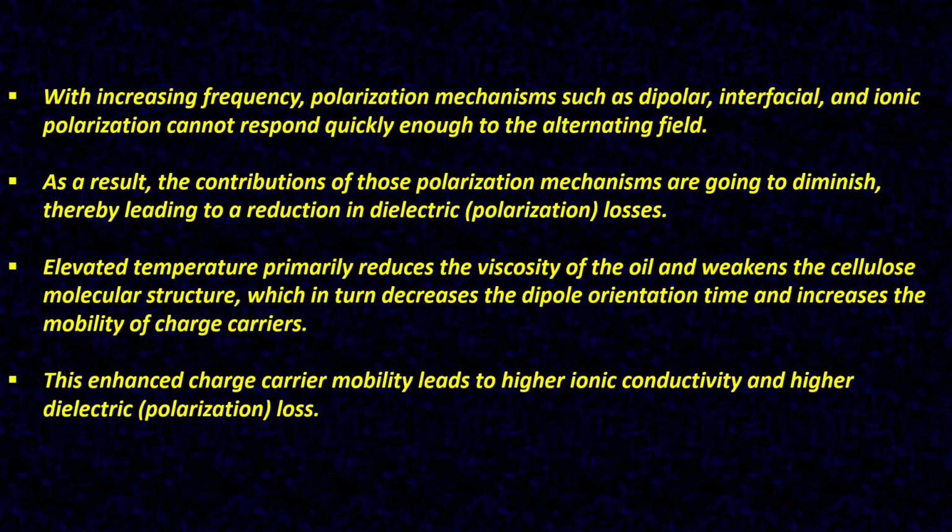With increasing frequency, polarization mechanisms such as dipolar, interfacial, and ionic polarization cannot respond quickly enough to the alternating field. As a result, the contributions of these polarization mechanisms diminish, thereby leading to a reduction in dielectric or polarization losses.